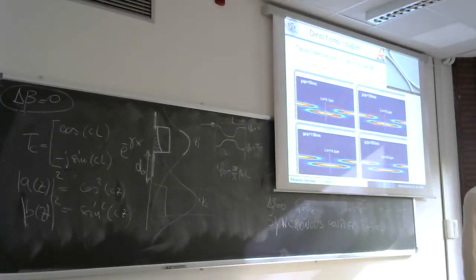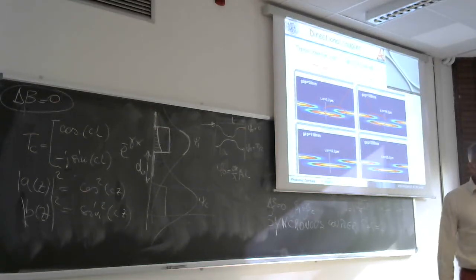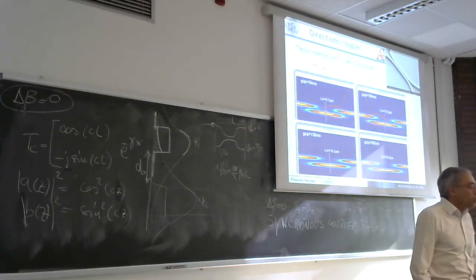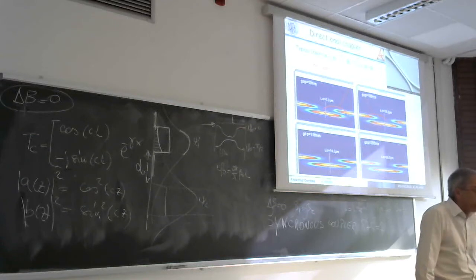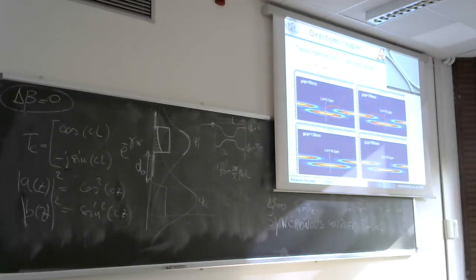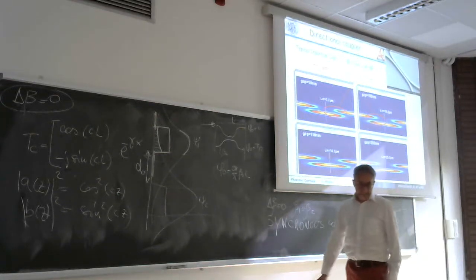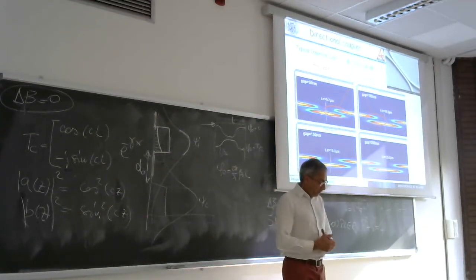But it's good. Is there a standard distance that you use conventionally? Just a rule of thumb, the width of the waveguide, or a little bit less than the width of the waveguide. It clearly depends on the contrast, but also the dimension of the waveguide depends on the contrast. So the gap equal to the width of the waveguide is a good point.